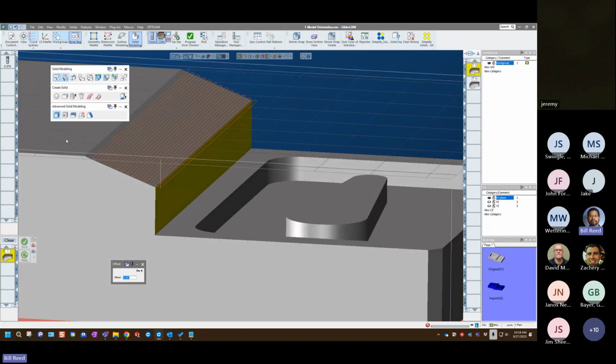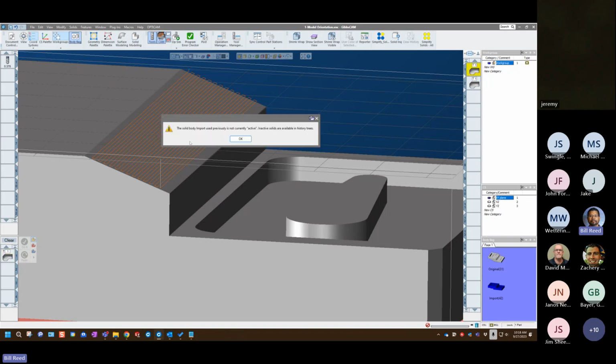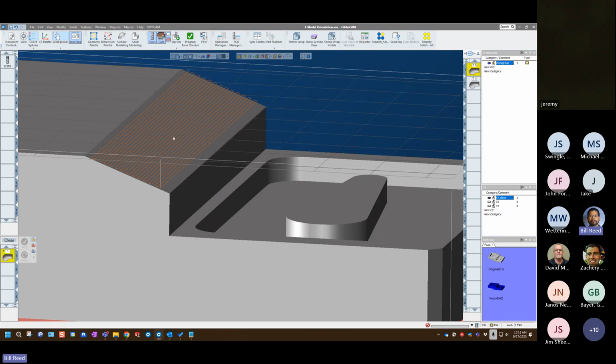And if you watch it, using the offset tool will actually grow your solid model and make it mathematically correct. So I can shrink holes, I can offset faces. So in this particular instance, I'm going to offset this face 1/8 of an inch. Boom, additional stock. So I'm going to go back up to my toolpath. Because I've changed the model that is associated with that toolpath, I get this error. It just simply means I've moved it or changed the solid body that was associated with that toolpath. Not a problem. Just click OK, reselect that face, and redo. There we go.